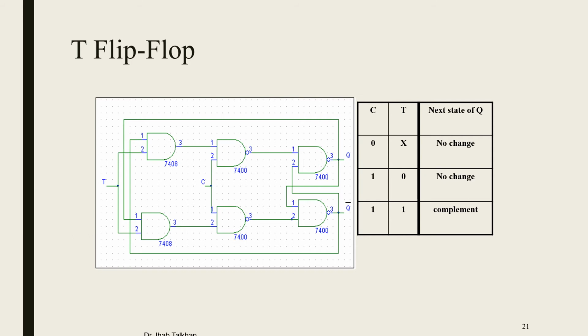Now we have 4 flip-flops, or latches. We have the SR latch, the SR flip-flop. We have the D latch or D flip-flop. We have the JK latch or JK flip-flop, and we have the T latch or T flip-flop. I mentioned T flip-flop or latch. It means that whenever you have a level input, it is a latch. Whenever you have a clocked input, it is a flip-flop. But both have the same functionality, the same truth table, and the same state table as shown in the slides.